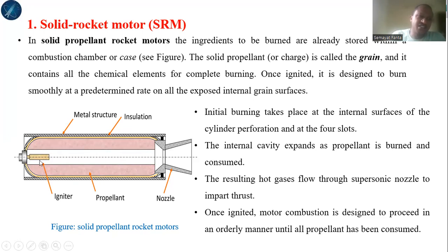Then we have the igniter. This is a small igniter which initiates the propulsion system. The igniter is made from some fire-sensitive material. We have two categories of igniters. We call them pyrotechnic igniters and pyrogen igniters. So what are pyrotechnic and what are pyrogen? We will see them. Anyways, this is an igniter, and some igniter attachments are here. We must attach the igniter into some igniter casing. Also, igniter design alone is a big project. So this is the solid propellant igniter.